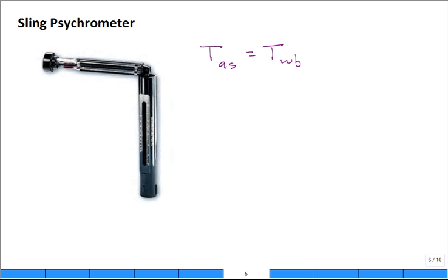It looks like it's about 64 on the wet bulb in this room, and it's around 74 on the dry bulb. Okay, well, they have a built-in little scale, and the engineers are pros at this. You have to find this scale is for low temperatures, this scale is for high. You line up the wet bulb and the dry bulb. So I said 74, true.